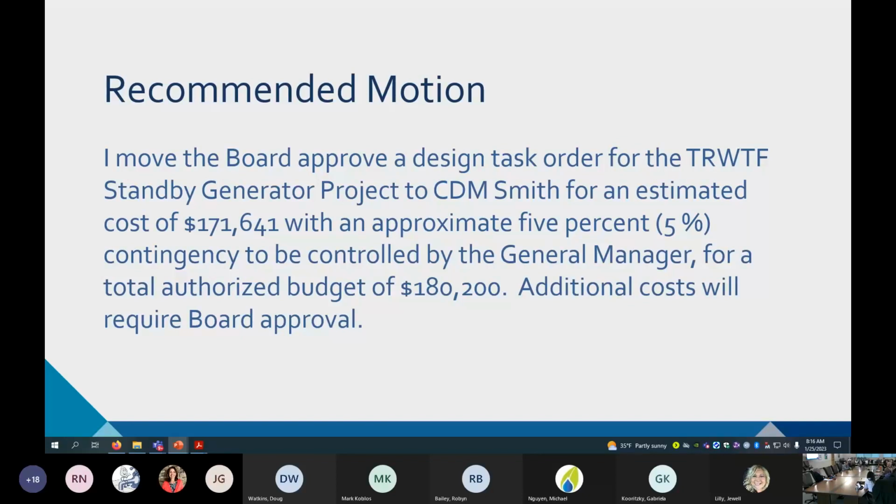You also have HVAC components, which includes a silencer, an exhaust that needs to penetrate the roof. And so you're going to have to figure out with a roofer how is that going to impact the warranty? Can we penetrate the roof, go through it? Mounting the silencer, which is a piece of equipment on the roof, needs to be coordinated with structural engineers. Installing large louvers as well. Are there any structural components that need to be switched or modified in order to make space for the new?